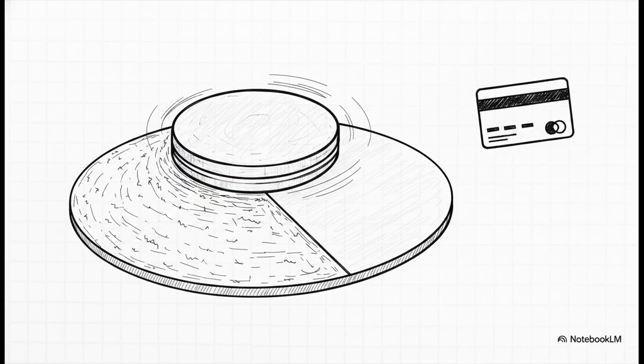So, using a process called chemical-mechanical polishing, we press the wafer against a rotating pad and use nanoscale abrasive particles to gently rub away those scratches. We do this until the surface of the wafer is atomically flat. It is perfectly smooth on a microscopic level.